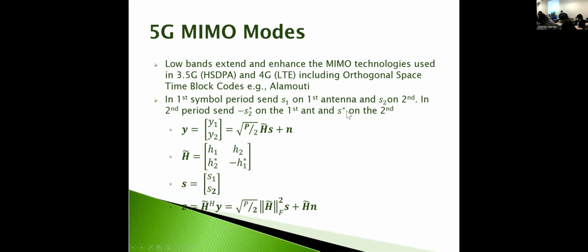And then on the other antenna, oops, I should have had a subscript of 1 on this one. We're going to send the complex conjugate of S sub 1 on the second antenna, swapping antennas at different time periods and doing this kind of complex conjugate along with a negative sign, but only on S2, I'm sorry. So mathematically, we can kind of draw this out.